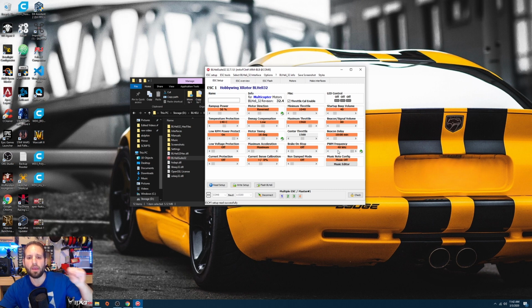Somebody took the time and effort to go into all that and program it so you have additional functions. And also, if you're running on a whoop or something smaller, there have been increased flight times from changing this to 48 kilohertz. So this would be a big thing to go ahead and try.